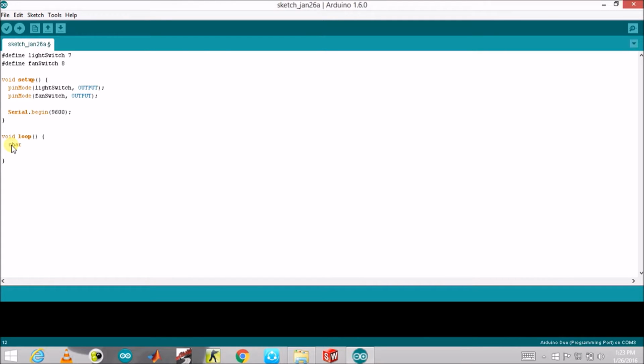Remove that slash. Then we will start by taking the input. If you see here, I have defined two character variables, one is raw input and another is input. I'm going to use the Arduino function Serial.read. What Serial.read does is it continuously reads the value it is getting from the serial data buffer. This has a bit of a problem: even if you don't give any input from the serial port, it returns a value of 255. 255 is the default value that Serial.read has. This read essentially reads bytes, it doesn't read a character, it reads bytes.